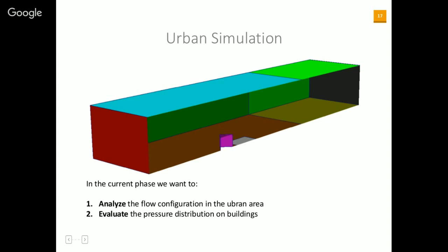And this is useful for two reasons. The first one is to assign different meshing refinement on your body. So this is the mesh part. And on the CFD side, the different coloring allows you to define different boundary conditions for your modelization, your fluid modelization.